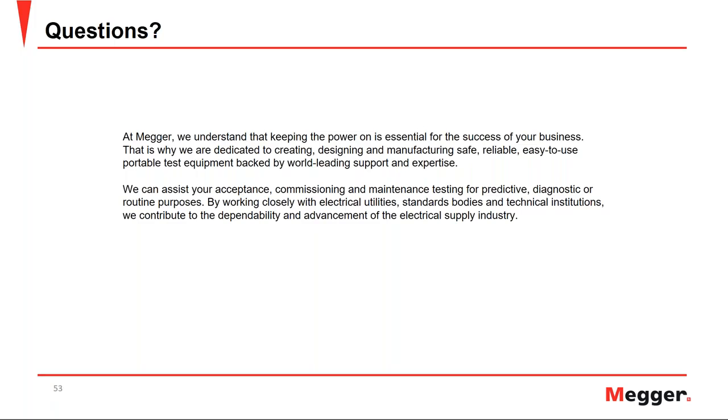Tip-up testing is also another way to get more information. When you run a power factor test, if you are not looking into the quality of the signal coming back from the transformer, you are losing some information. The instrument does that automatically for you. It detects any possibility of small partial discharges inside the transformer and indicates that you may find out more by running a tip-up test.